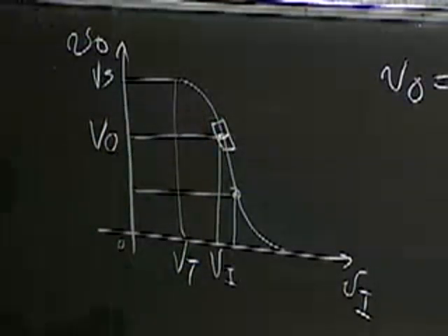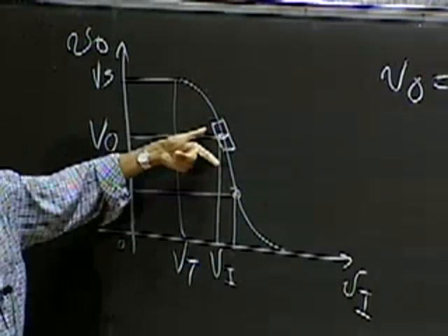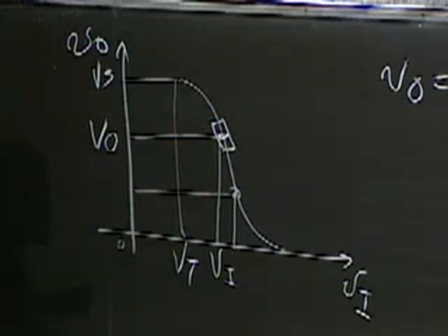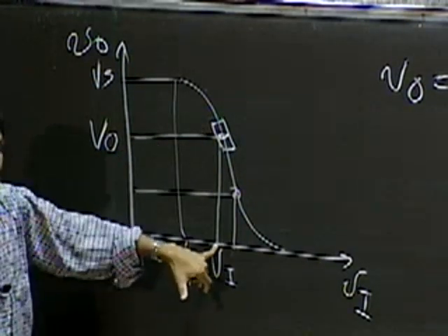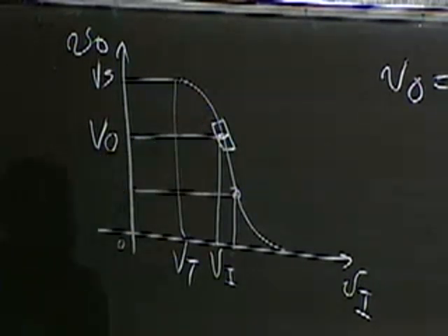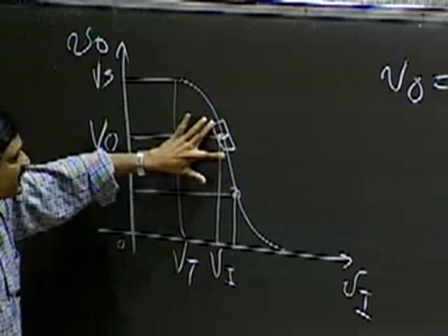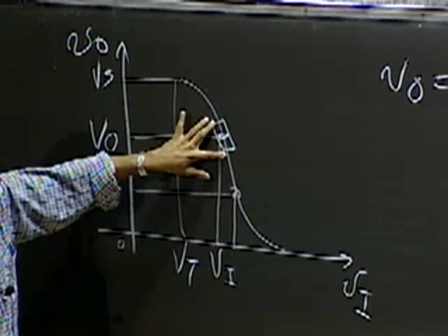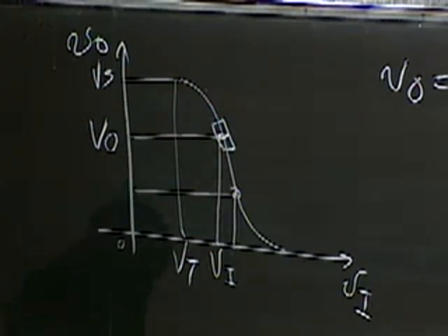Okay, this means that if I could work with very small signals and apply the signal in a way that I also had a DC offset of some sort, then I would be in a region of the curve. I would be delineating a small region of the curve, which would be more or less linear. Okay, this was a small signal trick. And what we'll do here is simply revisit the small signal model.